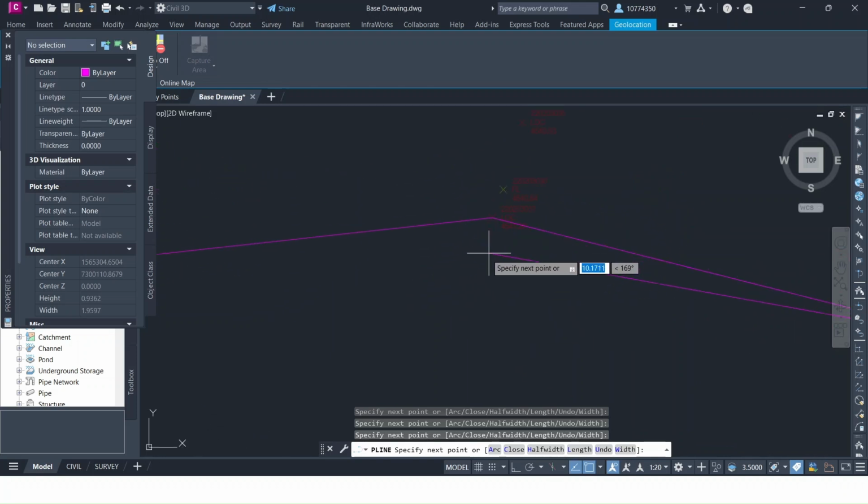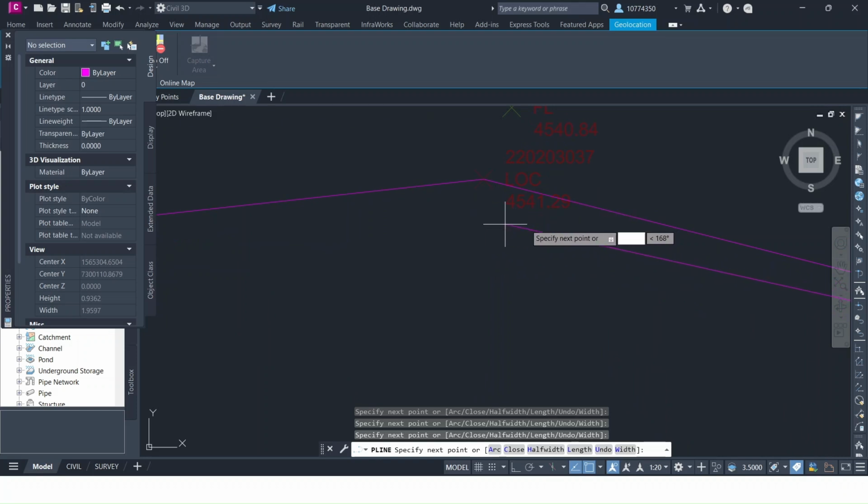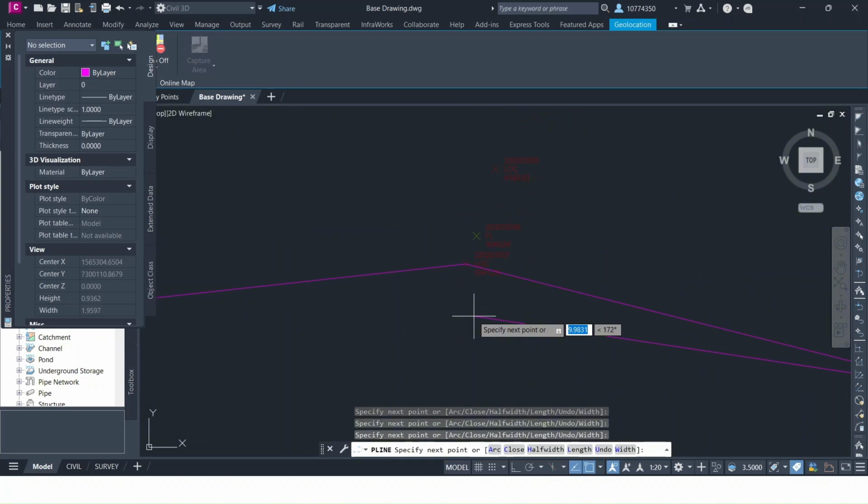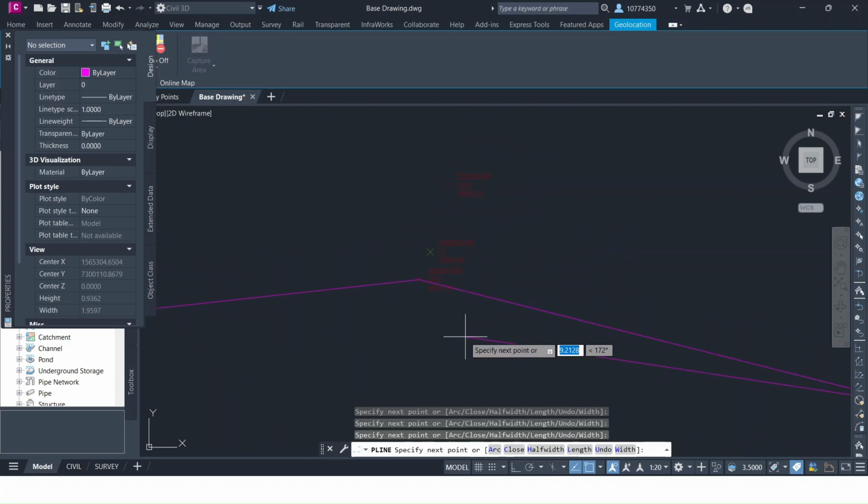So right here, I have a little bit of a problem. Whoever was surveying this just forgot to type it up as TBC. They most likely went to the LOC, then walked back up to the TBC and just clocked it as an LOC and forgot to change the label. But once you're looking through this, you can kind of get an idea. You're like, oh, that was just a mistake on their part. But anyways, I just want to point that out.